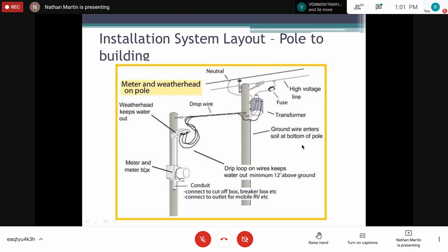The two will vary in that if you are talking about overhead, you're talking about another connection of triplex from another service cap. It won't be from the same service cap, because you have to come into the meter socket and out from the meter socket to the facility.